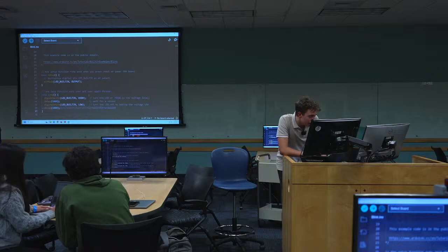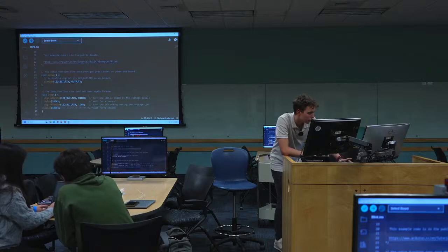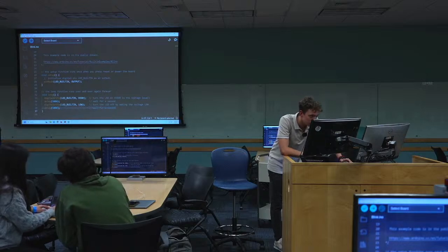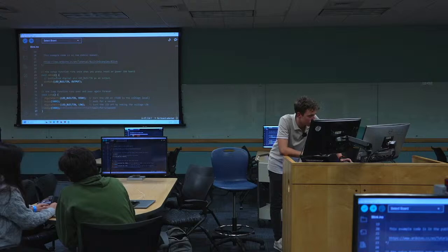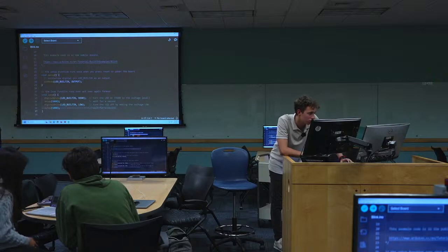All right, so you can see that there are two functions defined in this Arduino sketch: the void setup and the void loop. These are going to be the main ones we use throughout the workshops. This is how the Arduino IDE works that they built for us, fortunately. In the void setup we are going to list all the components that we're going to use. For analog components, which I'll explain in the first workshop, you don't need to, but for the digital ones like this one, you do.